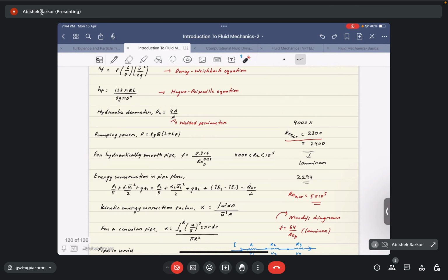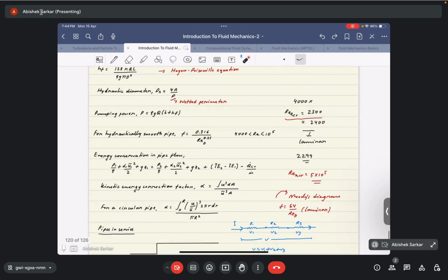and there we can find the value of the friction factor, where the friction factor now depends on the Reynolds number as well as the surface roughness of the pipe, which is usually represented by epsilon by d.